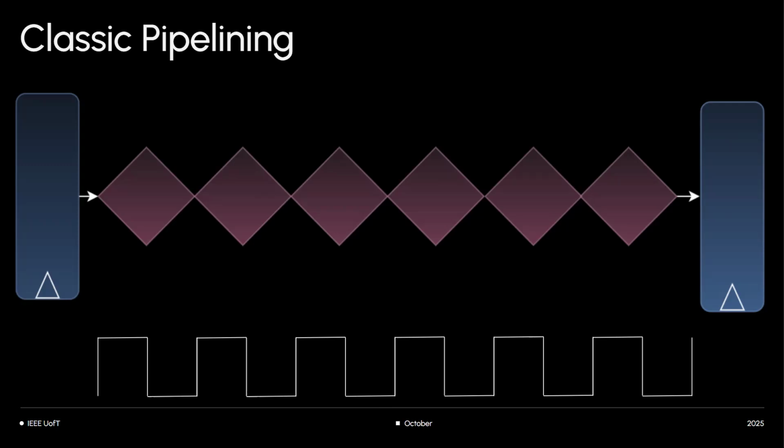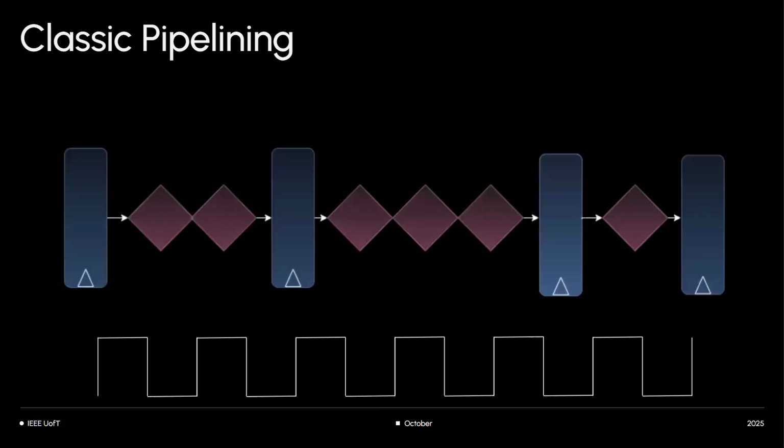So people ask the question, then why do we build synchronous circuits? Why don't we copy that idea onto circuits? It's closer to our brain, and that's how asynchronous circuits were born. So this is a classic pipelining idea. This is what most designers do to immediately increase the speed of any processor. They take that combinatorial circuit in the critical path, slice it, and then, pretty much like our cake example, they can bake more cakes per unit time. But what we're going to learn is black magic on how to make even this go faster.